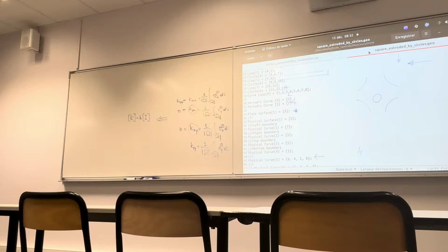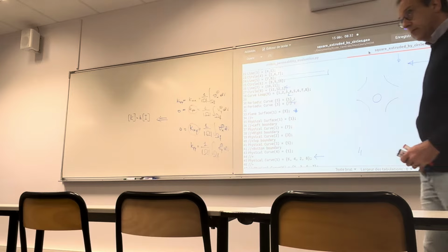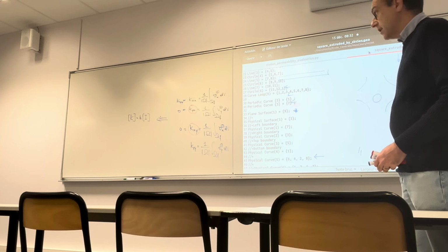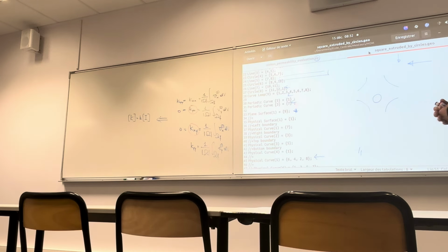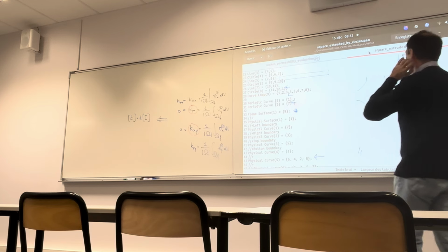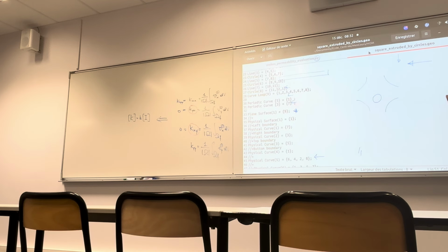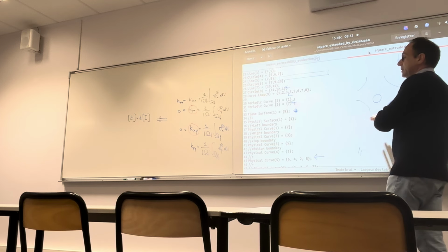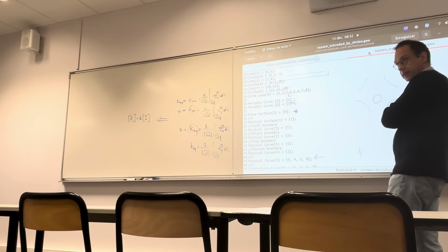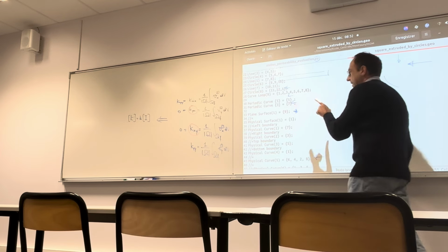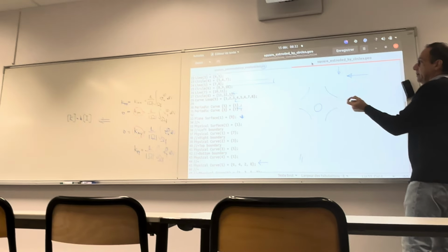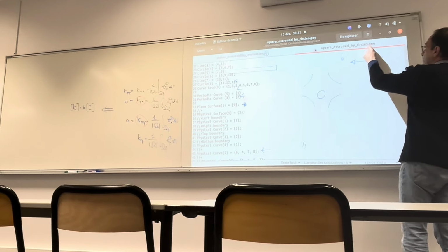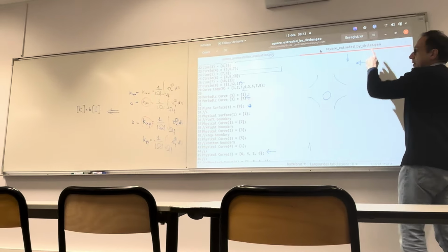So one thing I want to ask, you gave us the text file, so we have to run it in Python. Yes, we have to change it into .py. Probably, I don't know if it will run also like that, but I suggest you come back to the extension .py. If you run it like that in Phoenix, it will produce the result that we have seen together. Okay? But then you have to modify the script in this way to incorporate the circular inclusion. So first of all, you have to modify the geo file in this way.